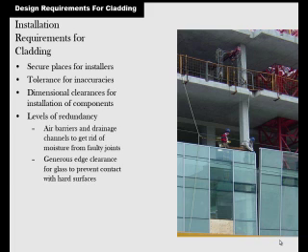Usually, some people don't. But you also need to have tolerance, because these panels here are prefabricated, and so there needs to be some wiggle room when they get it up there, because they can't just take it down and rebuild it. There has to be some wiggle room in case something's a little bigger or smaller, or they didn't pour that column in the right spot. They usually accomplish that with enough space in their joints, and then they'll fill the joints up with some filler or caulk or stuff like that.